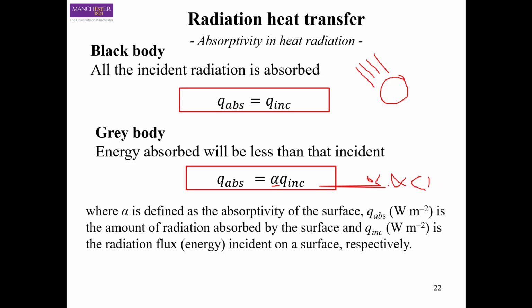Okay, it has a value between 0 and 1, and it has no units. Now in most of the calculations, alpha is not equal to epsilon, because they are two different properties of the material. But there can be situations where epsilon is actually equal to alpha. It means that the absorptivity and the emissivity of the object are equal, if the two objects have identical temperature and they are emitting and absorbing light at the same radiation wavelength.